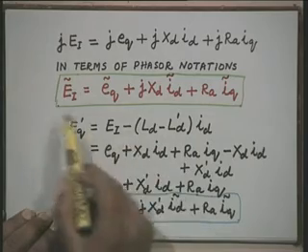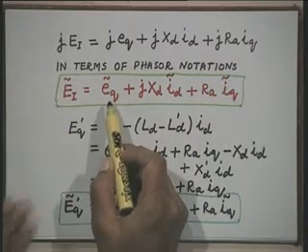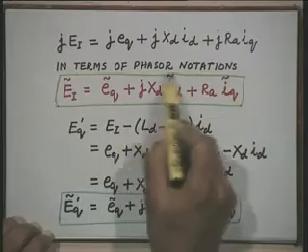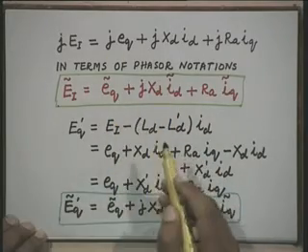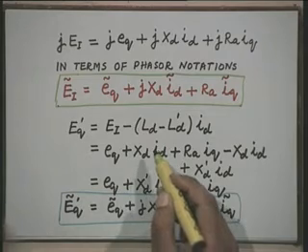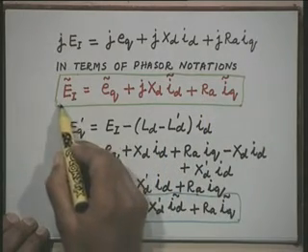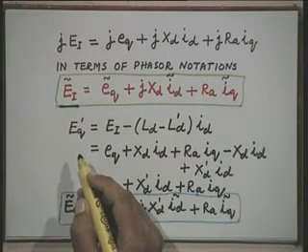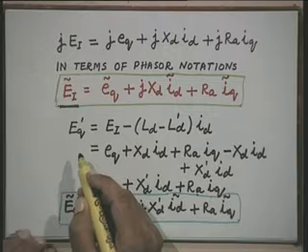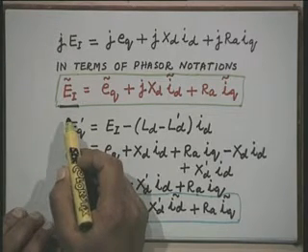Now, when you see this equation here, you will find actually that this is E q, which is along the q axis. This term is also along the q axis, that is I d when it is multiplied by j times X d comes across the q axis. This is anyway along the q axis. Therefore, this term E I, which we defined as voltage proportional to field current, is lying along the q axis.